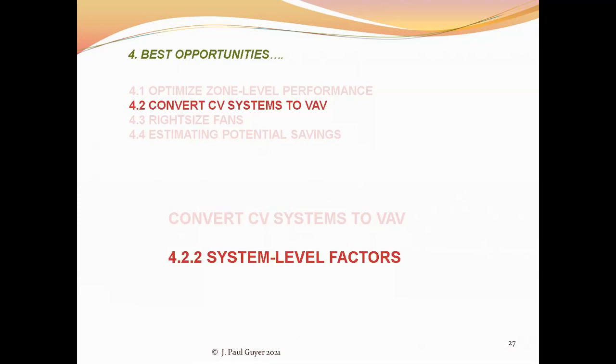The energy savings are a benefit of such a conversion, but the focus ought to be how to make the HVAC system meet occupants' comfort needs. When soliciting bids from contractors, it can be helpful to look for nearby buildings that are similar in age and design to your building and determine whether VAV conversion has been implemented in those comparable buildings.